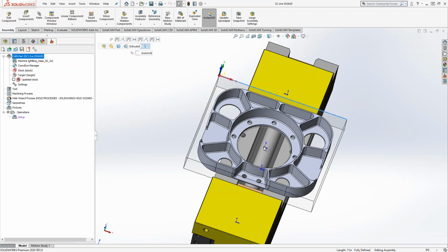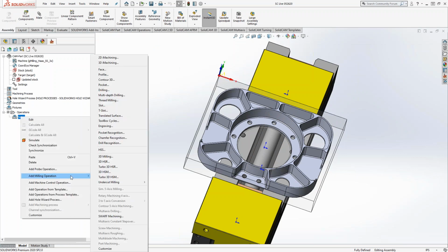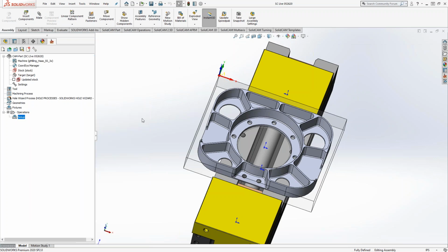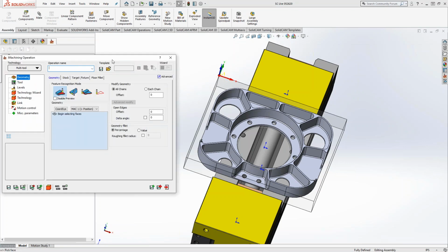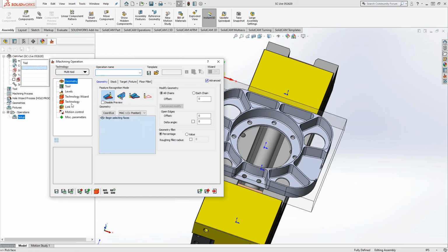There's a question there from Clinton. Is there a way to adjust the lead-in distance on an iMachining toolpath? The XY clearance on a stock model when it is plunging moves from clearance. Is there new functionality for the lead-in distance, Kevin? Are you talking about the arcing distance, or how much it comes off the floor, Clinton? The arcing. Okay, that would be in the technology or the link page.